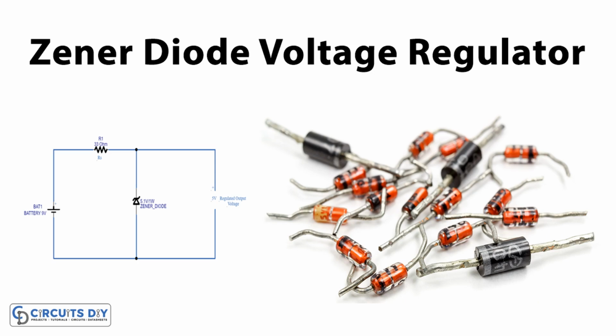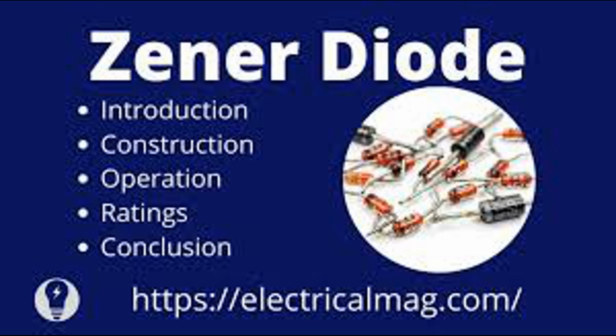Conclusion: Zener diodes are essential components in electronics, renowned for their ability to provide stable voltage regulation and protection across a wide range of applications. Their unique ability to conduct in the reverse breakdown region allows them to maintain a constant voltage, making them invaluable for various tasks. Here's a summary of the key points. Key functions: voltage regulation. Zener diodes are widely used to provide a stable output voltage in power supplies, ensuring that sensitive components receive a consistent voltage despite variations in input voltage or load conditions.